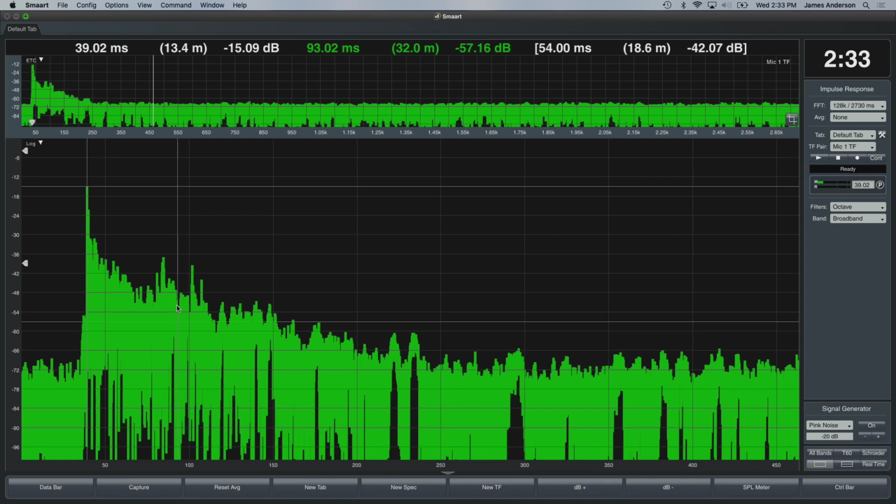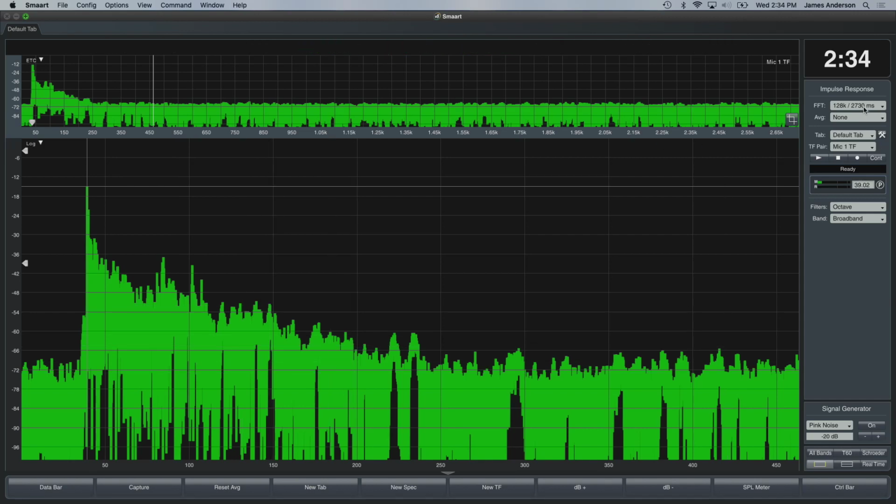I know people that do impulse response measurements, acousticians, that will do much larger time constants. The time constants we've got go all the way up to a 512 here, which is about 10 or 11 seconds long. And run multiples of it. So it's a type of measurement where you start the measurement running, go get some coffee, and come back. But the whole idea is to maximize that dynamic range. They're trying to do acoustical studies, what's going on acoustically, and not just broadband.